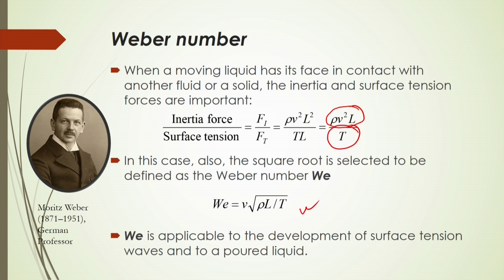You have to know how these bubbles are forming, whether they are uniform in shape, and when they will reach maximum size and stabilized form. If the critical Weber number comes to 1.2, you will see that in an air-water system the bubbles will form stabilized. So in that case the Weber number is very important.